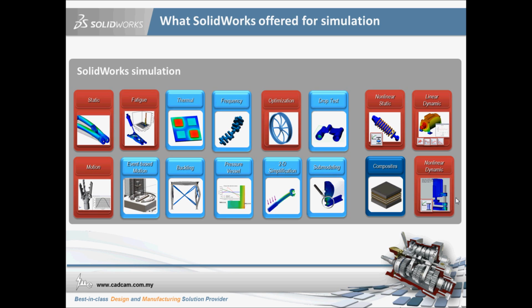To go more advanced, we have linear dynamics, non-linear statics, and of course non-linear dynamics. Non-linear dynamics can be applied in rim testing. As I know, in rim design there is an impact test to fulfill as part of the requirements, so non-linear dynamics allows you to perform this form of simulation.